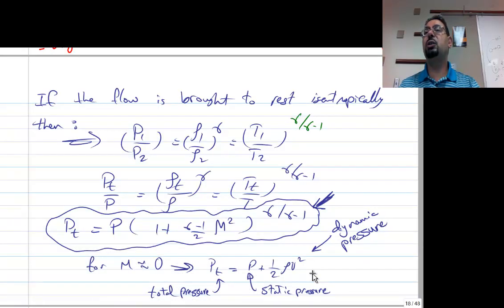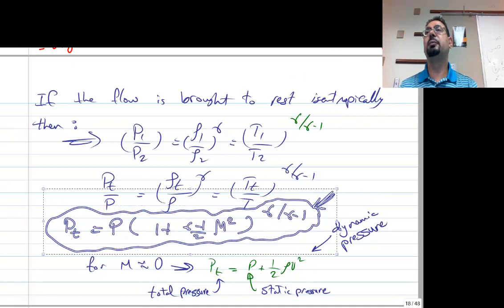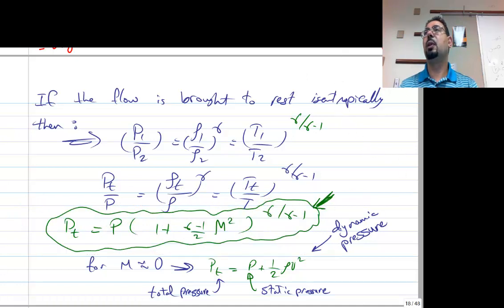And will the results be different if incompressible flow is assumed? So before today's lecture, you could have used, because we had this in the previous homework, remember? First homework? We should have used this. And at that time I told you this was the last time you're going to use it. So if you cannot use this equation to get the velocity in the wind tunnel between P total and P static, what are you going to use? You're going to use this one. Right? So will the results be different? Yes. This is the accurate one. This is the approximated one.